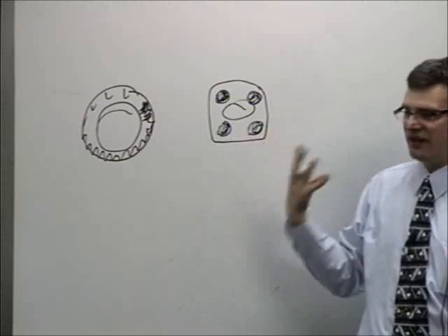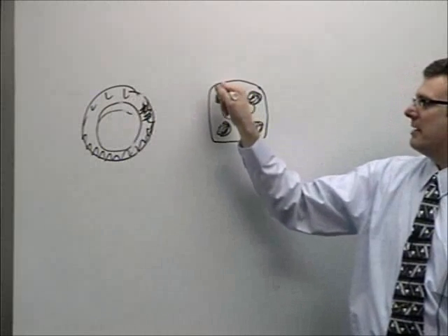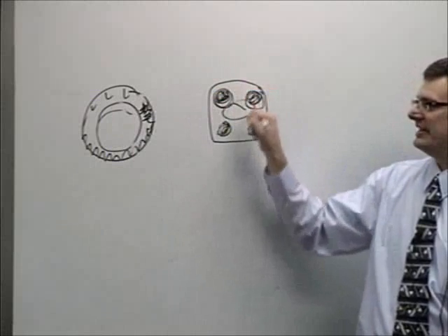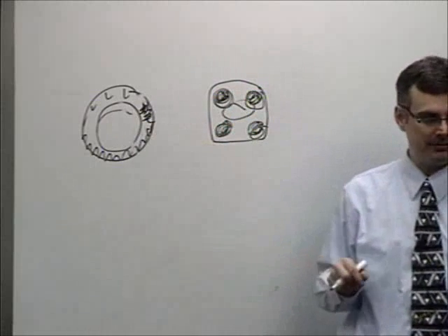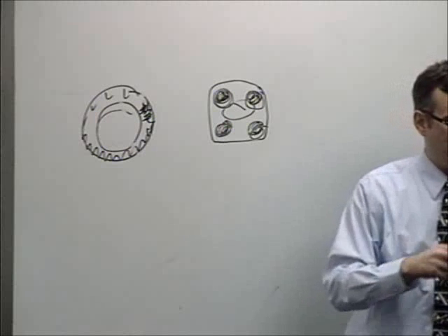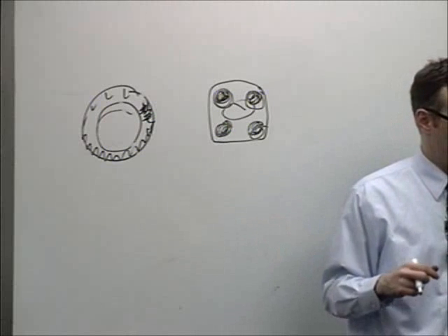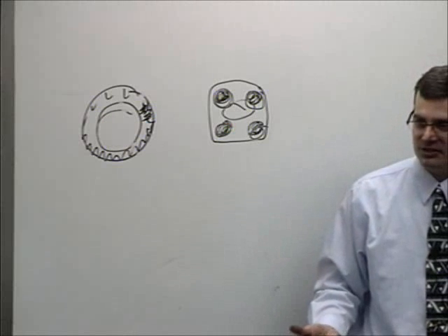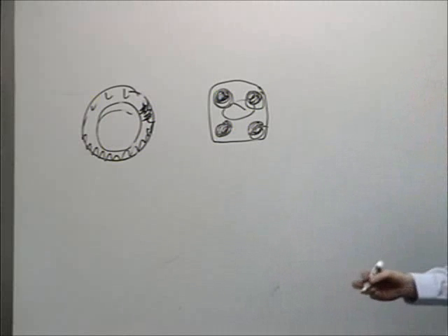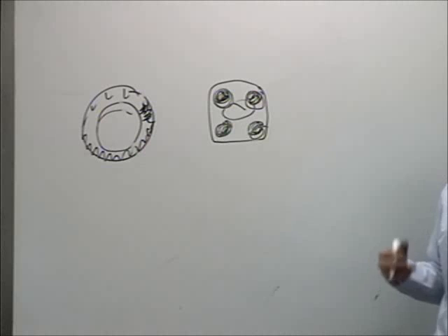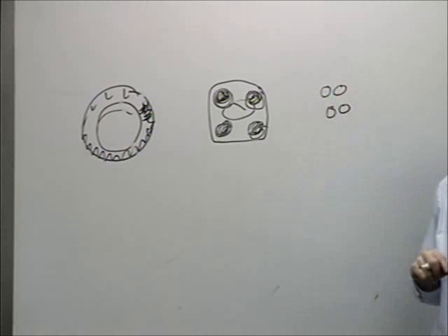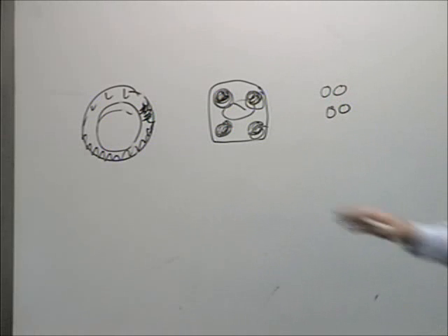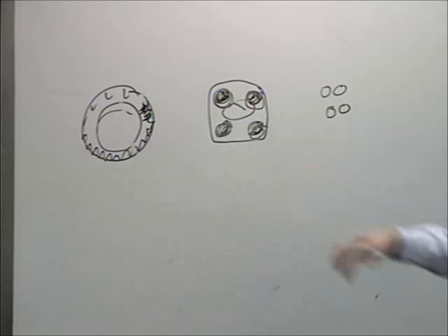that you use less volume of material and you can get more perimeter space on your tiny cables, on a bundle of tiny cables, than you can on one big cable. And thus, over the miles and miles of runs of cable, you save millions and millions of dollars as an engineer. So depending on how long and how high the voltage is and how much loss there is, you'll see sometimes 2, you'll see sometimes 3, and then you'll see sometimes 4 on the really high-powered lines. Anybody ever notice that walking around?